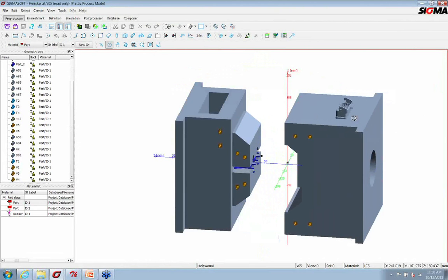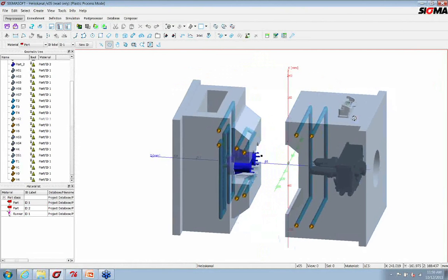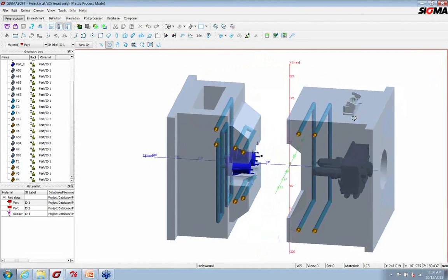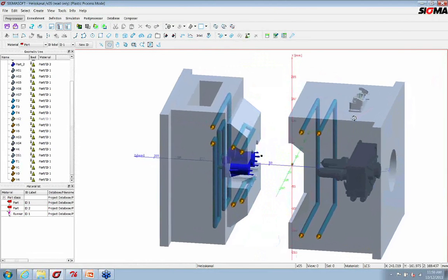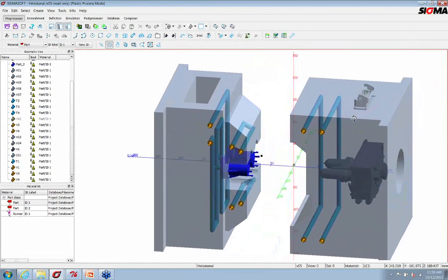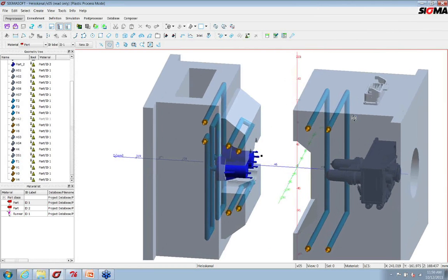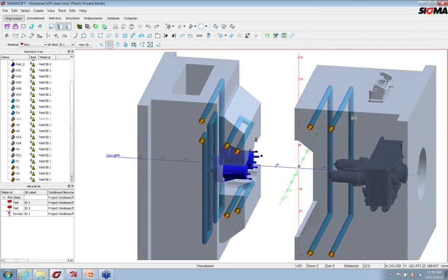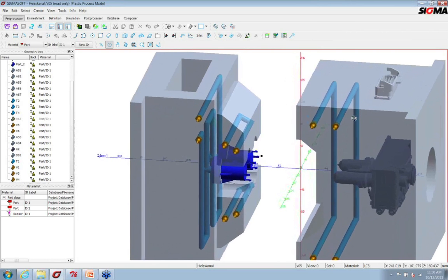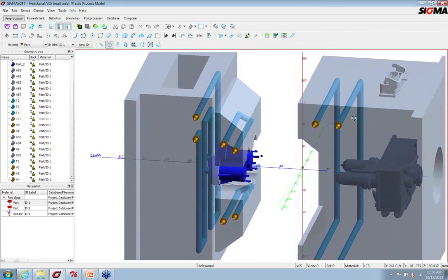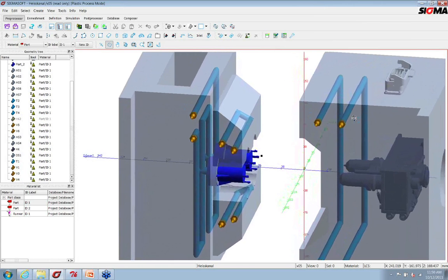Okay, so now we have our mold opening, and a multi-direction mold open there. Now we switch to transparent. You can actually see the cooling channels that run through the tool. You can see our hot runner manifold over there on the right with our drops. And the parts are in blue. So we're making blue parts today. Or I guess at this point they're cold, right? So they can be ejected.